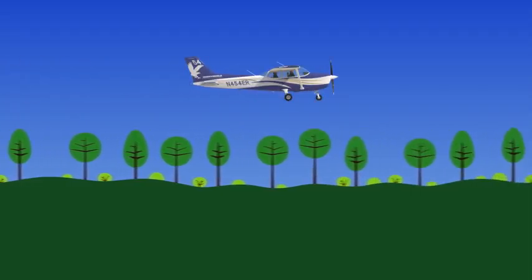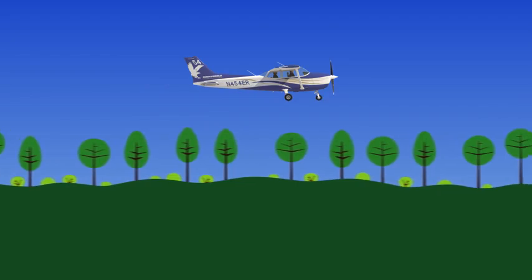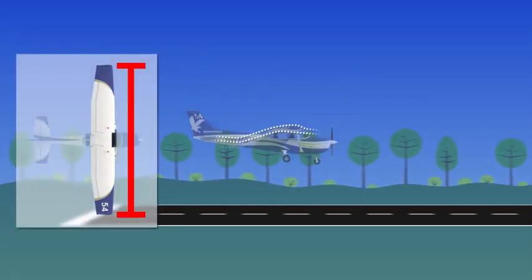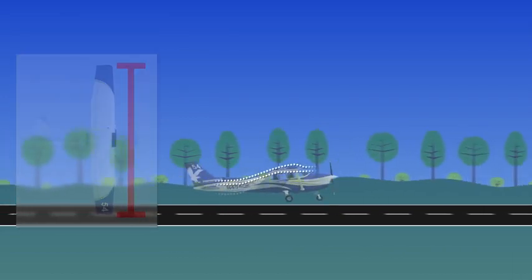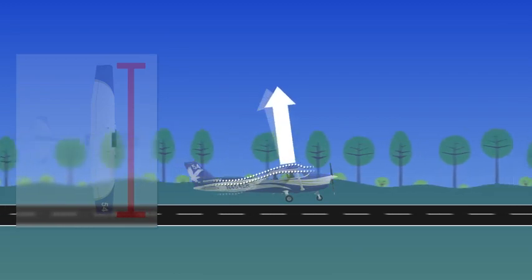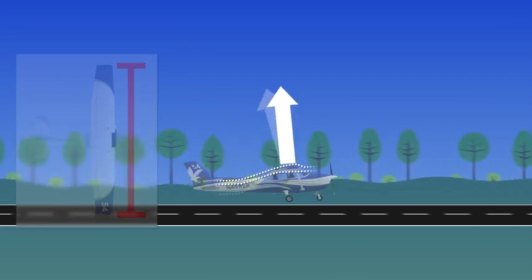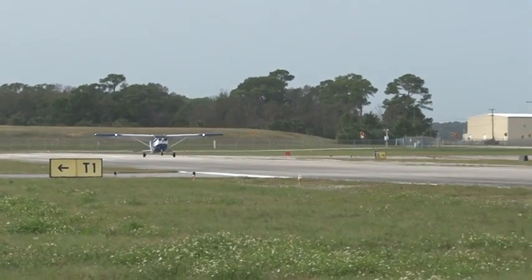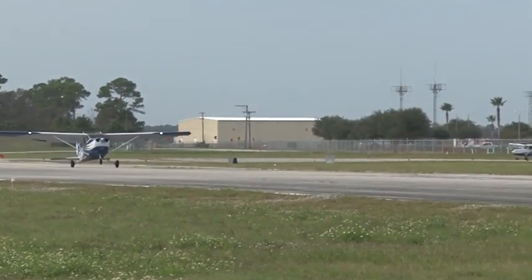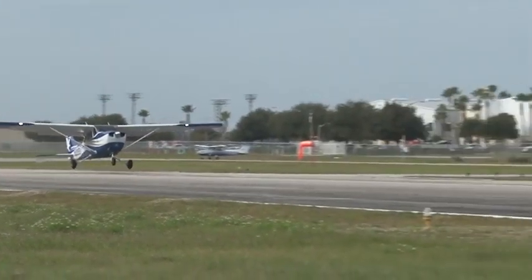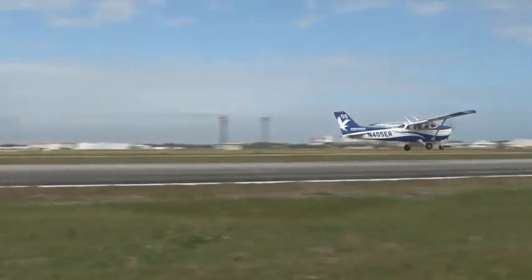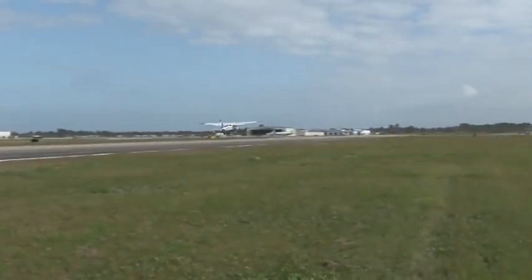One way that a pilot can experience reduced induced drag is by flying in ground effect. When flying within a wingspan of the ground itself changes the downwash of the air flowing over the wings. This shifts the lift vector forward and reduces the amount of induced drag. Pilots can take advantage of ground effect when performing a soft field takeoff. This lets the airplane lift off the ground before the regular liftoff speed. However, they'll need to hover over the ground for a few seconds to increase their speed before they can continue to climb out.